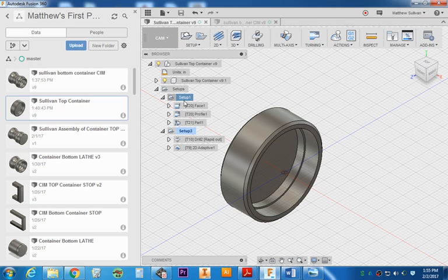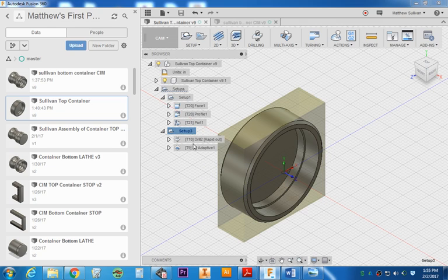As you can see right here, we have one post-process for the 3 lathe operations. We have another post-process for this part for both the milling operations. So be aware, we have 2 post-processes for both parts. Therefore, we will have 4 post-processes altogether.